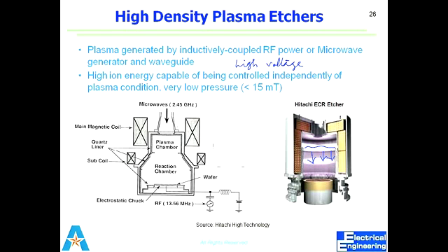I have a question. Since we need a deep trench like this, which is directional, why do you choose isotropic etching instead of DRIE or RIE? It's not. We can do only RIE instead of taking small isotropic steps several times. Okay, only DRIE. It's just an example. I'm taking it as perfectly isotropic, but you don't have a perfectly isotropic process anywhere. So when I say deep RIE, it's still RIE, but it has cycles. It means that maybe you go deeper in this way, but at the same time you go lateral this much. So DRIE also has some isotropic etch.